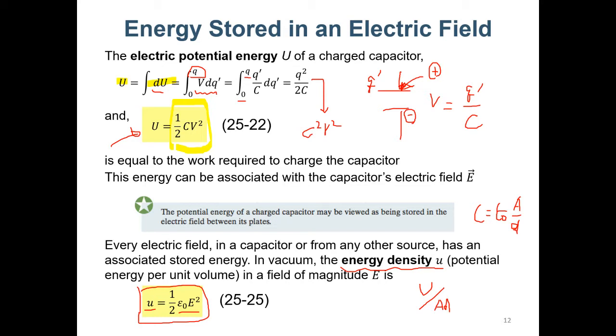because maybe you will consider a digital circuit, and maybe you have an inverter, and then you use a clock to drive it. Maybe the clock is f. So the power consumption for this inverter, with C load, will be P equals f C V squared, something like this.